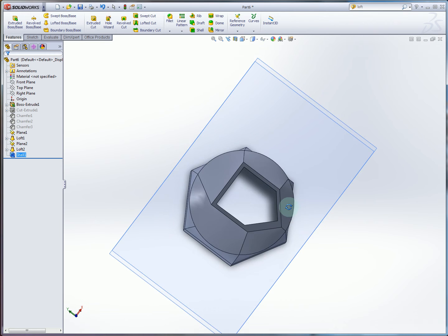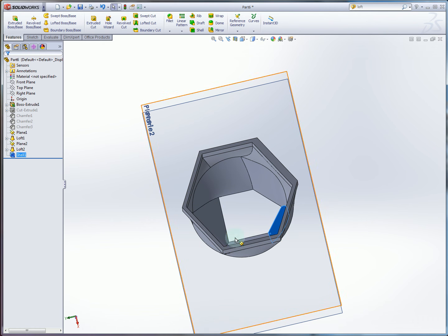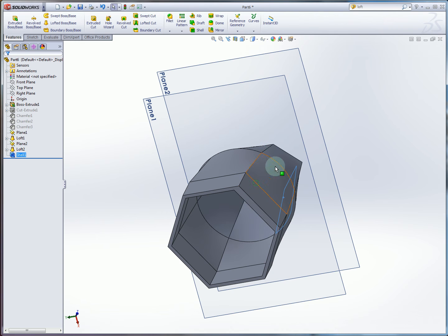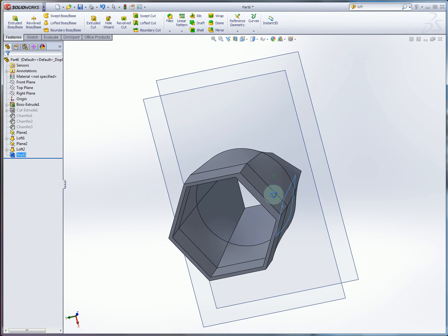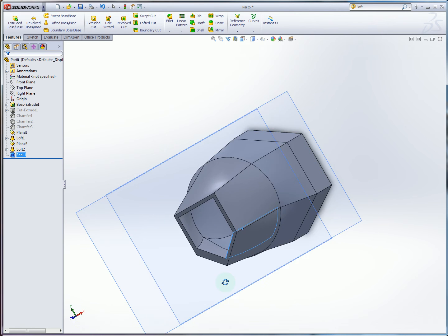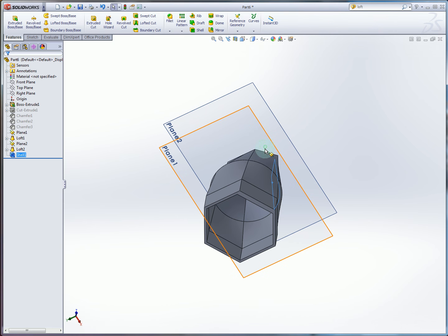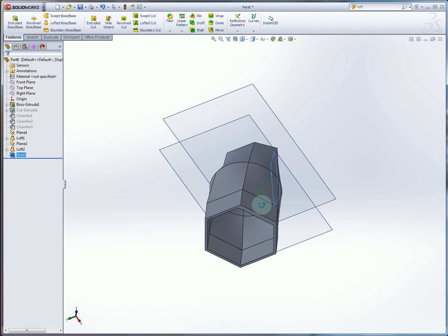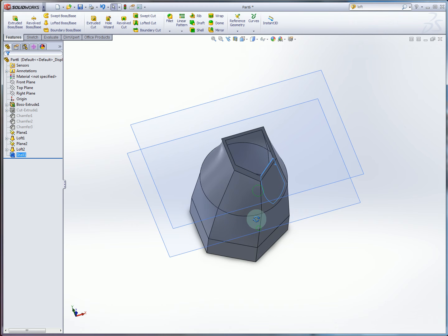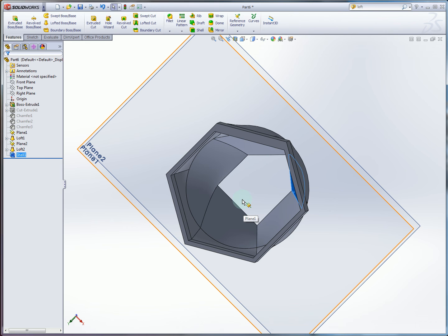It'll chug along, and we can see the effect is that we've removed these end faces, and we get this nice 0.1 inch thickness around the side, except for the stretch of faces that we chose as a multi-thickness, which you can see as this extra thick section of 0.2. You can choose an arbitrary set of faces to produce that extra thickness, and that can be really useful when you have, let's say, a counterbore on a round part, like a thin extruded part, or anything where the section is a consistent thickness except for a few simple spots.